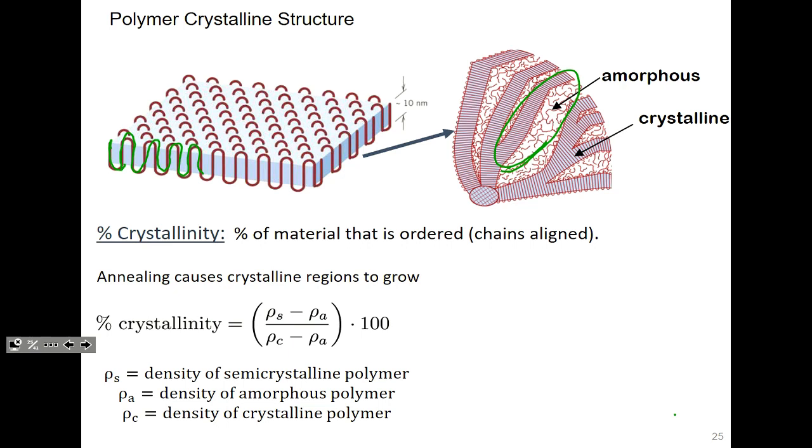And so how does that happen? Really stochastic, okay? Depending on the temperature, the way you cool the polymer, what you could potentially have are crystalline areas like this, and then it could somehow be like this. That's absolutely within the realm of possibility. And so when you end up with these semi-crystalline materials, you're interested in controlling the percentage of amorphous content or the percentage of crystalline content, which is just 100% minus the amorphous content, right?